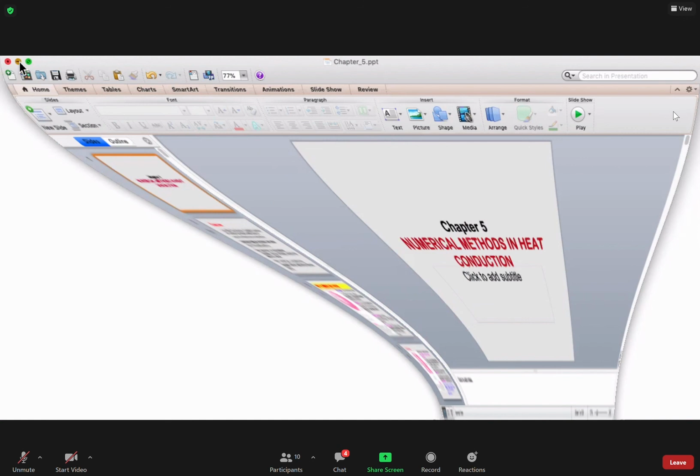But you can go back and make sure you use this graph. This graph gives you the temperature at the mid-plane, at the center of the wall. And if you need the temperature at another point, you can use this graph here, okay? Therefore, the figure is much easier to use as an engineer, but that one-term equation given to you is only for the case where the Fourier number is more than 0.2. But probably the solution here is making some assumption. No problem, sir. Thank you.